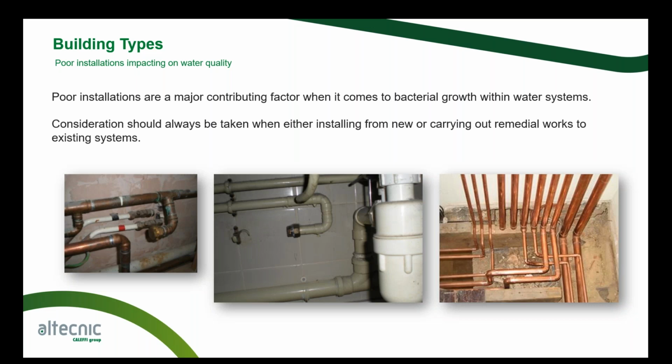The one on the far right side looks like a good install. It's nice, new, shiny copper. But what it does show is that there is pipework running close to each other. There is no lagging on there.